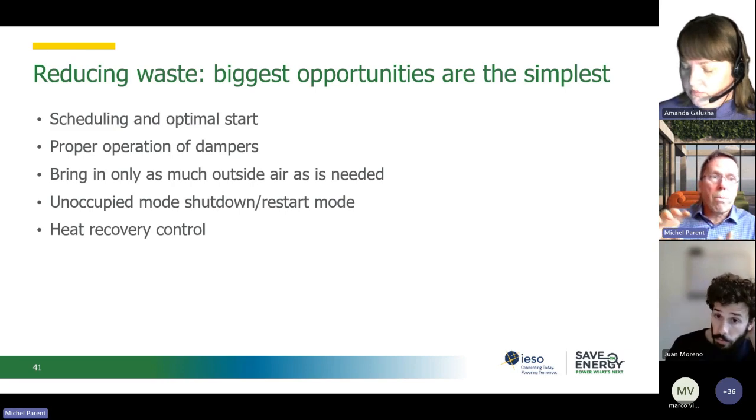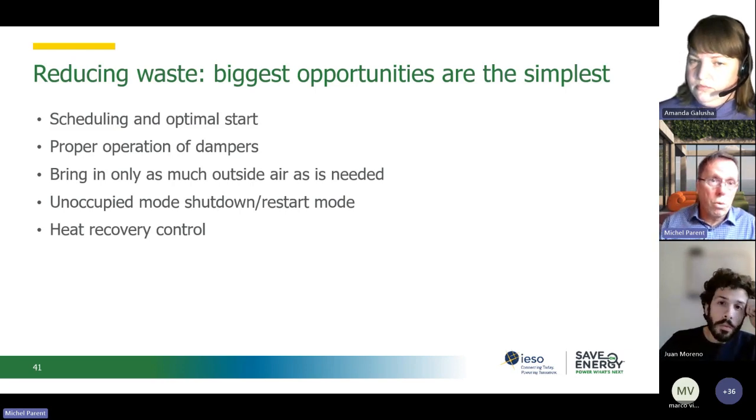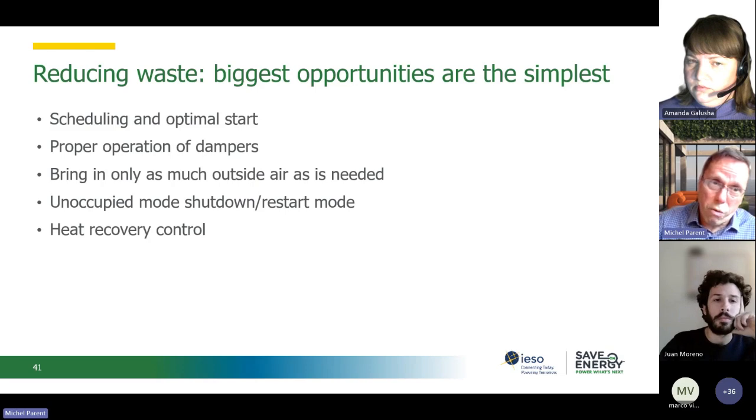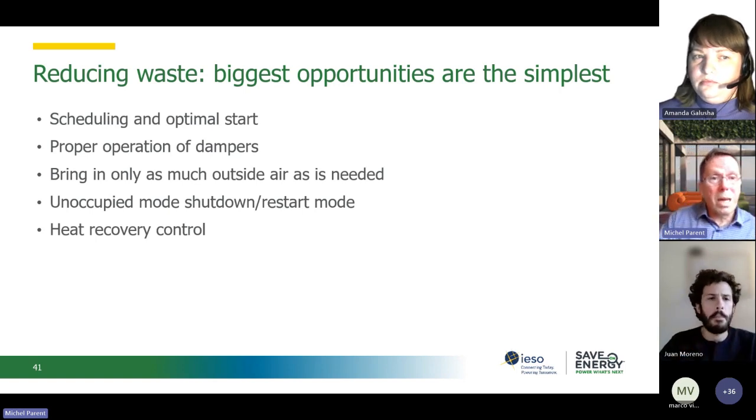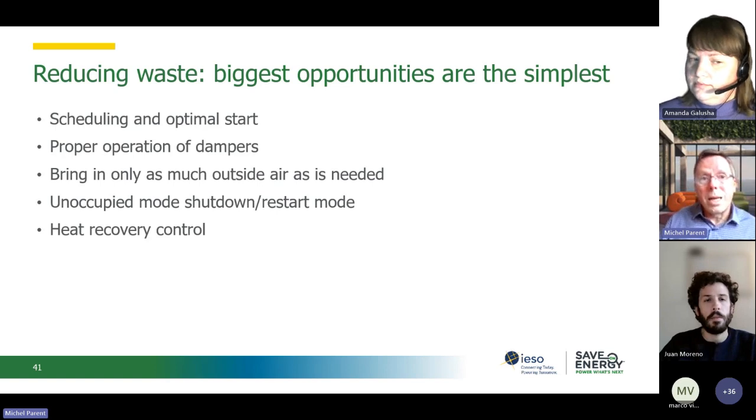When you look at your HVAC, check proper operation of dampers. Do you provide enough outside air? Are your dampers controlling properly? Sometimes you don't provide enough outside air, oddly enough. And even though it may not bring immediate savings, it may put you on the path to identify savings.